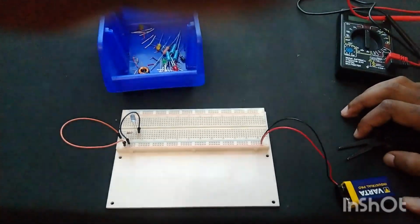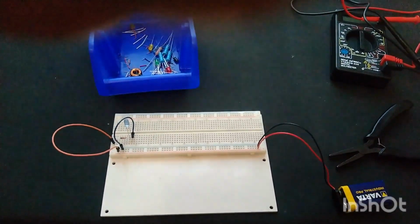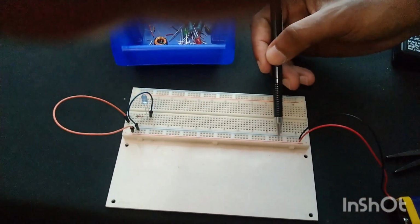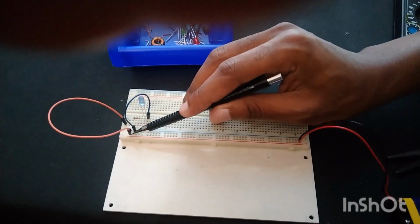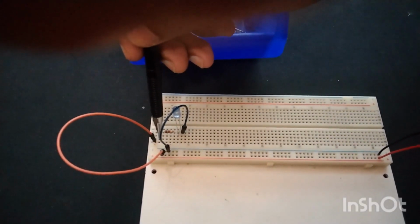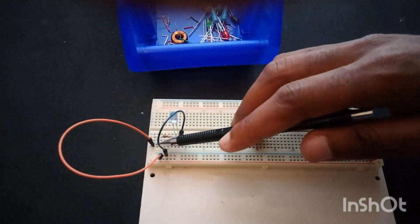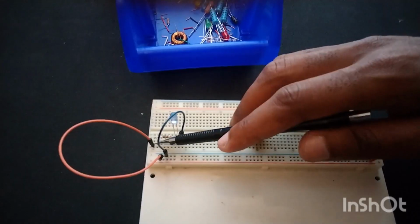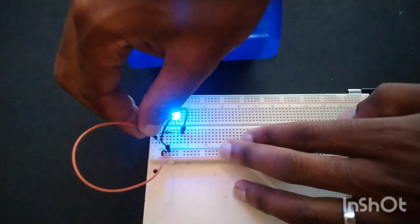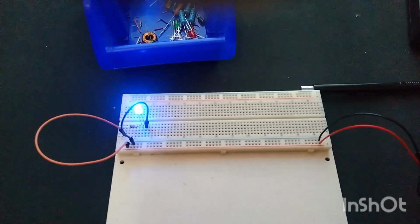Now let's check where the problem is. You see, the voltage runs from here all the way up, and then it gets here to the orange wire. Then it jumps over to the resistor. Then it runs from A to C. You see where your mistake is. Your wire is above the resistor, it's not in line. Now let's try to fix it. You see? That's why you made a mistake.